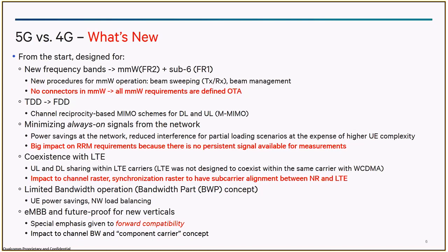Is this more prominent for millimeter wave? No, this is in FR1 and FR2 both. Especially channels greater than 3 gigahertz are actually very wide. Less than 3 gigahertz, they are typically 20, 50, less than 100 megahertz. But greater than 3, they are all greater than 100 megahertz channels. And in that, the FR1 UE could be limited to a 50 megahertz block only. Those are some of the concepts that people have thought about. How actual deployment might happen, that can change.